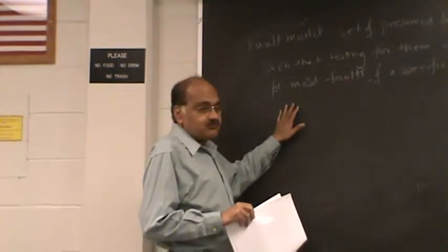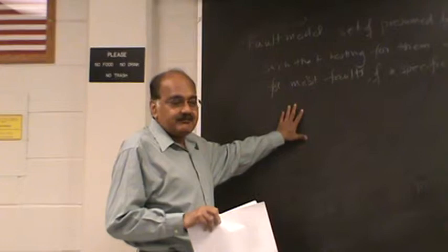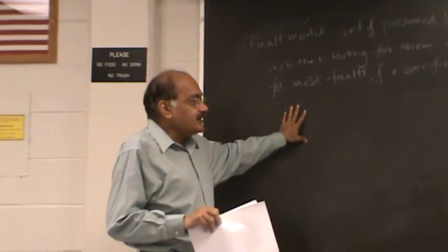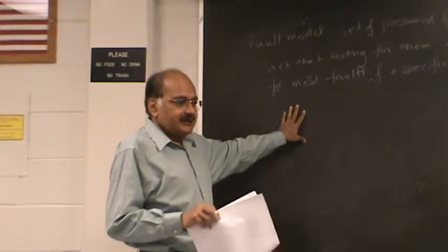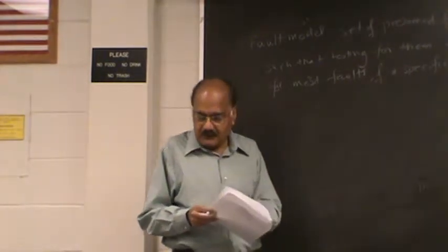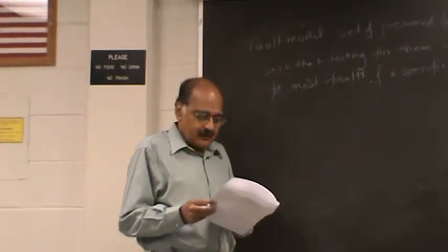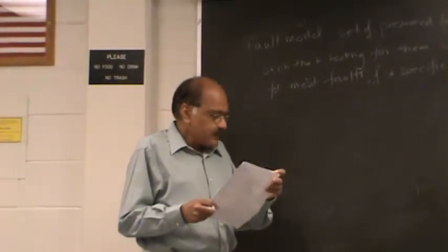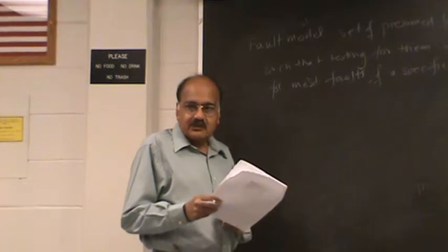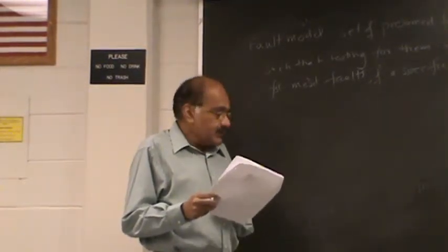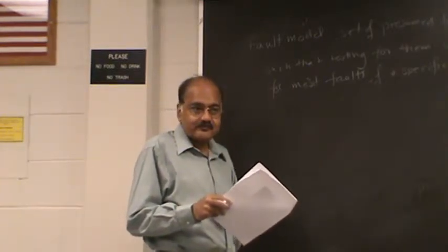possible types of defects that could arise. Now, to decide if a certain fault model is good or not, it takes a fair amount of research. For example, if you wanted to verify the applicability of stuck-at-zero, stuck-at-one fault modeling, you could simulate defects at a lower level, perhaps use SPICE, and find out what is the impact of those defects, shorts, opens, introduced resistances. And you might find out that quite a few of them will actually show up as stuck-at-zero, stuck-at-one faults.